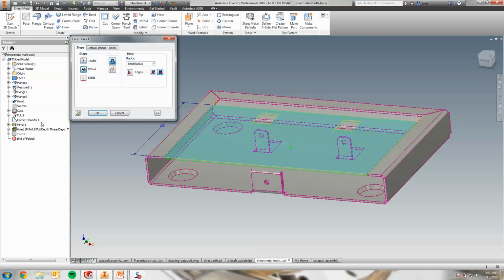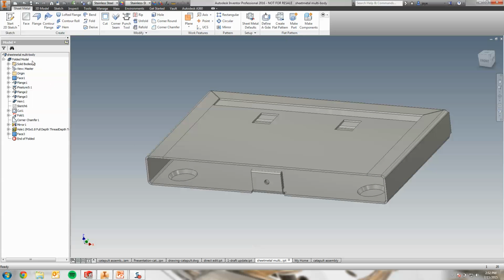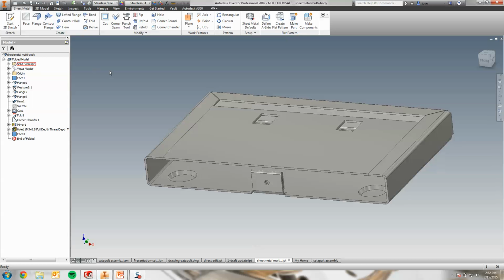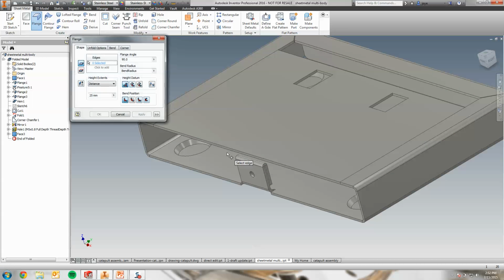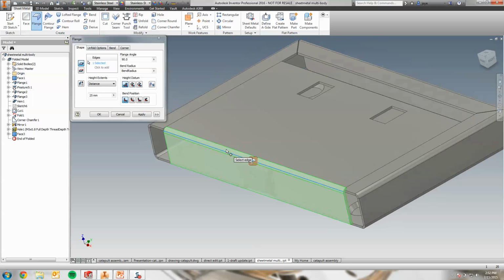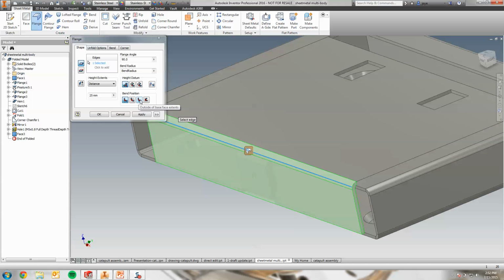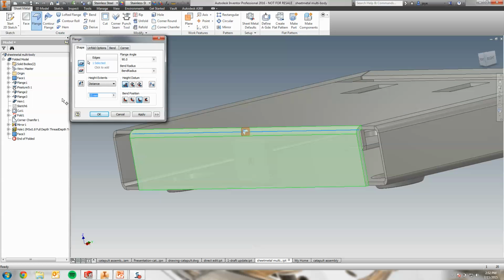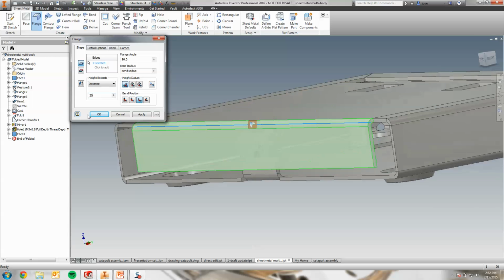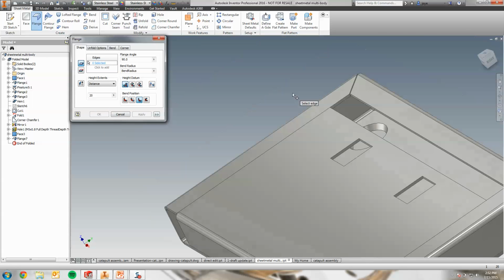Whoops, let's go back in here actually. I need to click on this new solid. This is a new feature now. So I'm going to do an entirely new solid. Now you can see in my solid bodies folder it says quantity 2. And now from here I can add some other features within this second body. I'm just going to adjust my bend location, and let's say maybe my length, like so. I like that, so I'll do apply.